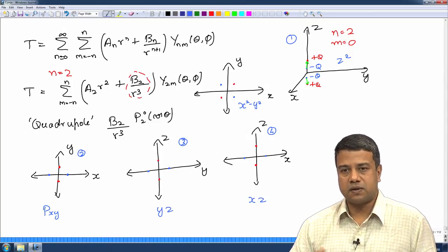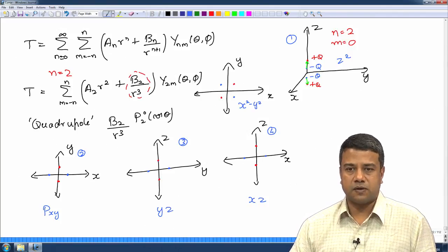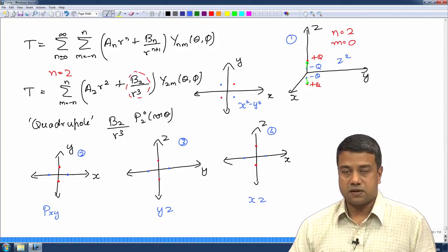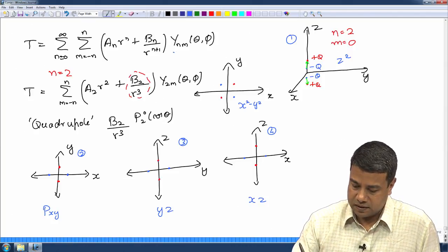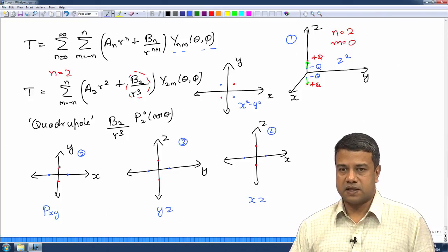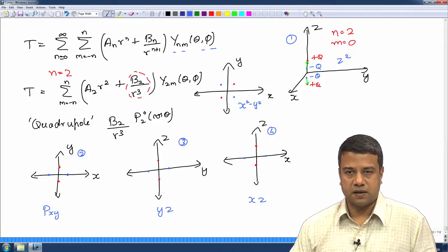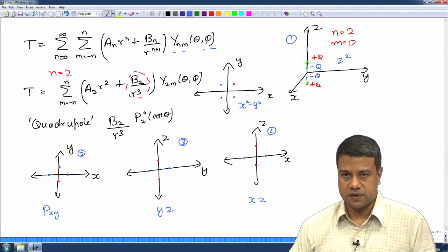You can have a 1-to-1 correlation between the solutions for the delta functions, the sources and sinks, and the Legendre polynomial expansions. Since all of these are orthogonal to each other, any temperature field due to any source can be expressed as a linear combination of these. That is precisely what we did when we solved the problem for the heat conduction in a composite material.